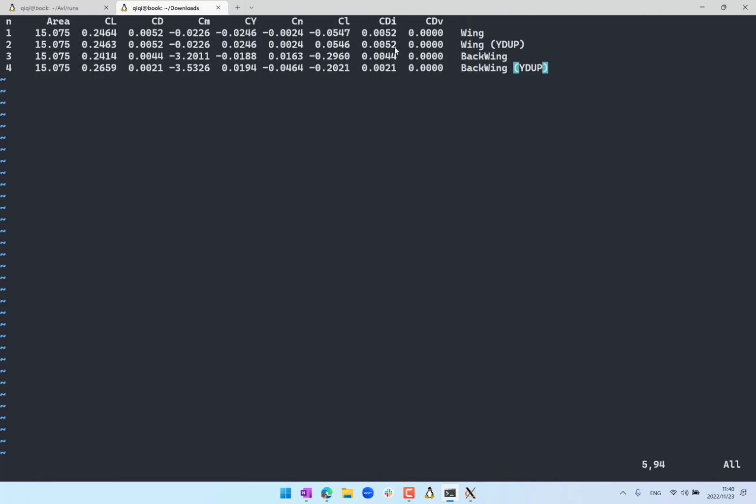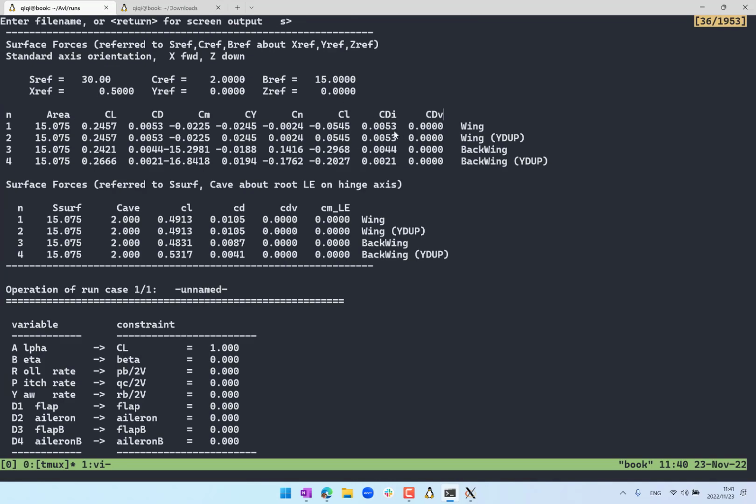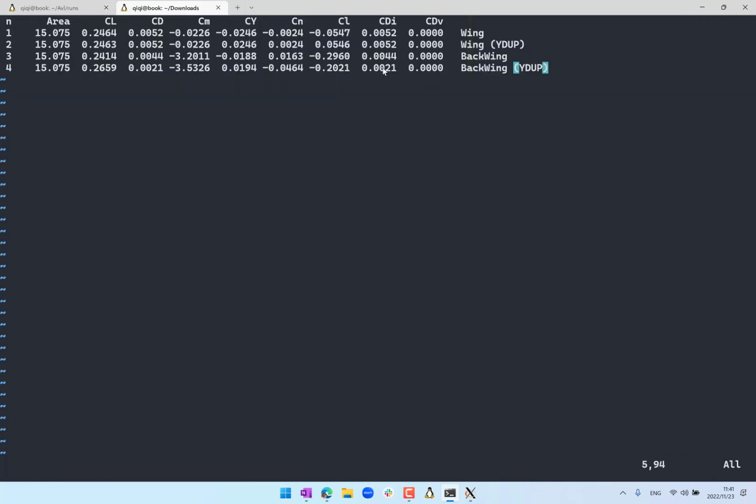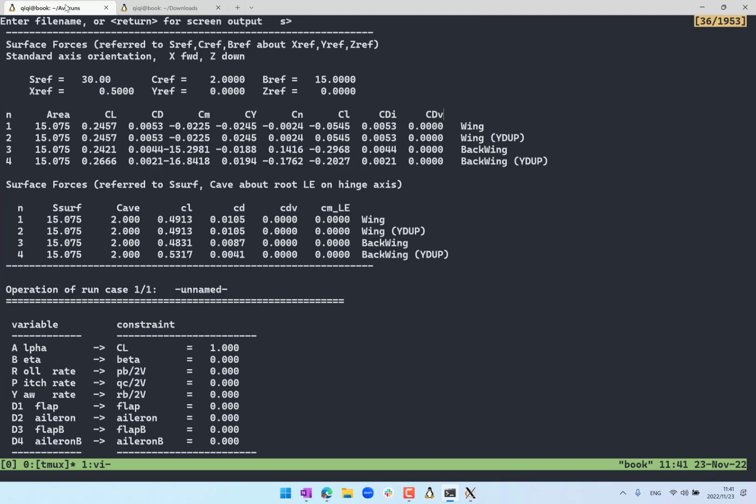That's a little bit more than what we had before, because the airplanes are so far apart that the effect of the airplane behind now has basically zero effect on the airplane flying in front. While when they are not that far apart, the tip vortices from the airplane behind still have a non-zero effect on the airplane in front. Now they are so far apart that the induced drag reduction coming from the airplane behind is basically zero. And the induced drag reduction on the airplane behind, 4421, is still the same. All right, so that's a good sign.